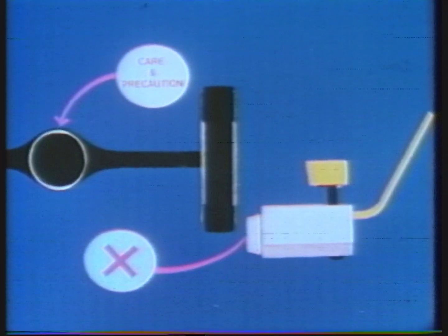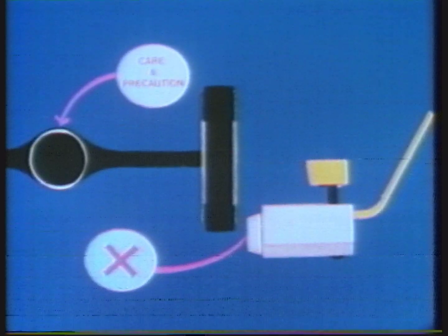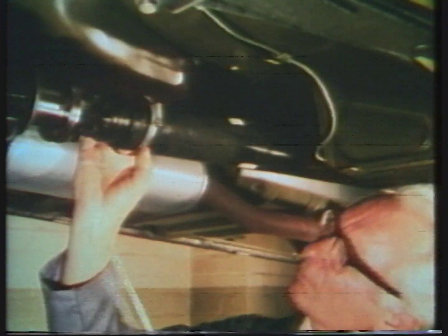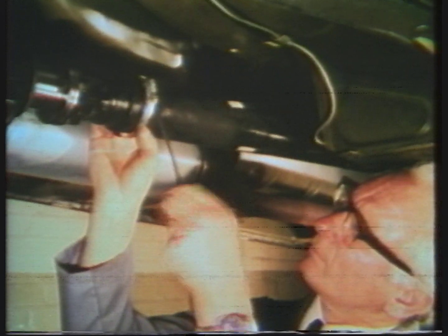If the vibration is at the rear, remember the need for great care to protect the differential during wheel balancing. If the prop shaft is suspect, then check balance, using the Jubilee clip method described. If necessary, go on to check the runout of the rear axle coupling.